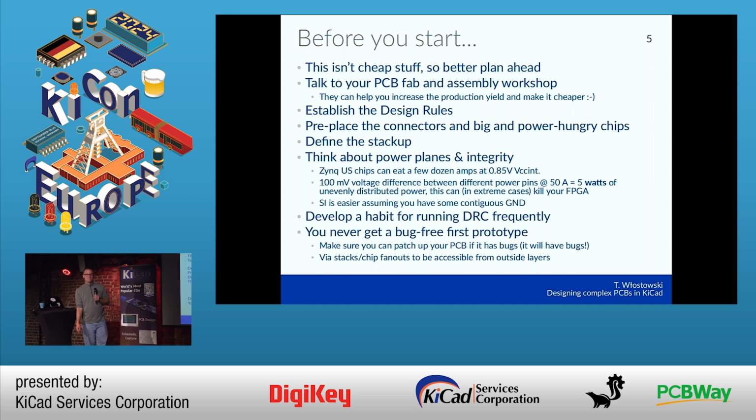Think ahead. These things cost. It's maybe not like the cost of taping out a chip, but let's say if you want such a design as the one that I showed you in the picture, prototyped reasonably fast, let's say in 3 weeks, you should prepare like 6,000 euros, not counting the BOM, just for the PCB manufacturing and assembly. So plan ahead, because mistakes at some point become expensive.